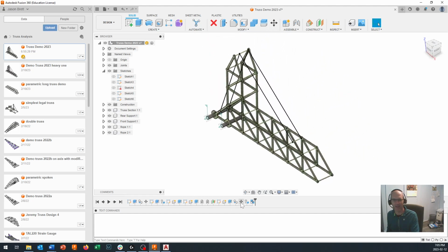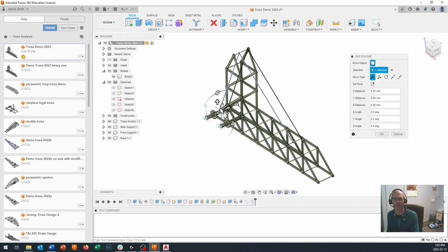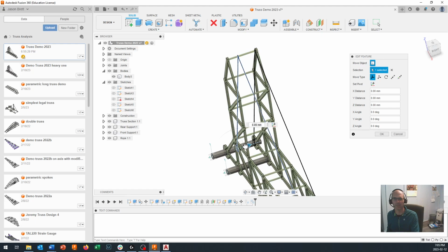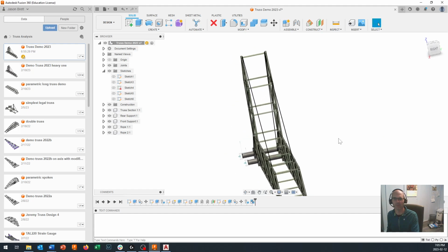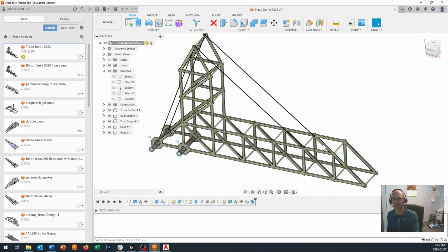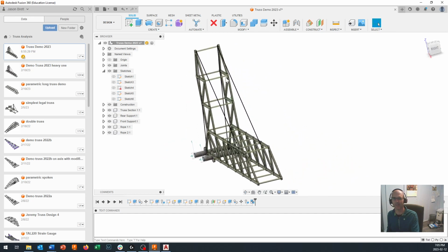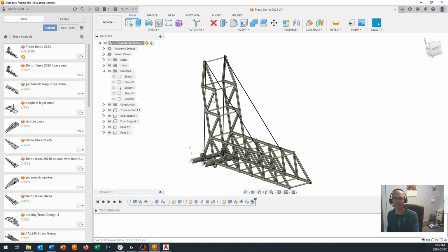You'll notice that because I used surface to surface modeling, all my cross members remembered to move along with me. And now up here, when I moved those members apart, I can move that another 20 millimeters. Don't want to move 25. Must be zoomed out a little too much, or there we go. 10, 20. They're 20 millimeters wider apart right now. And now I can go back and do another simulation and ask, am I stronger at a 60 millimeter gap or 40 millimeter gap?